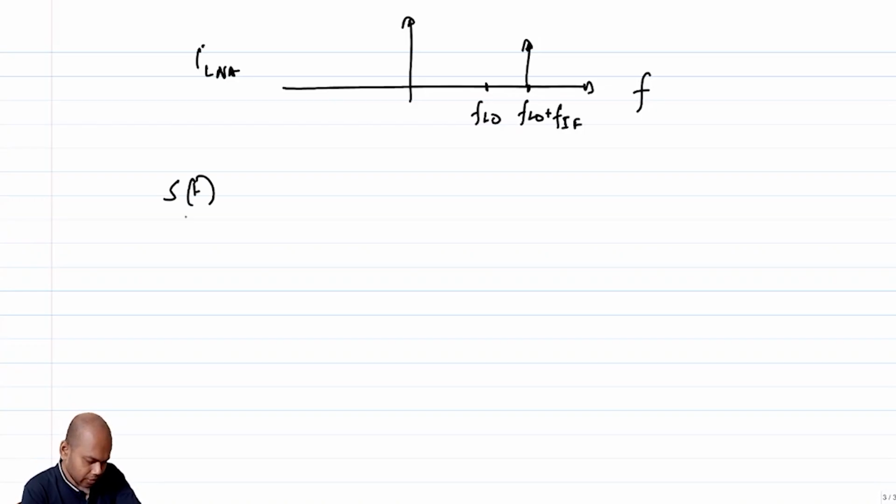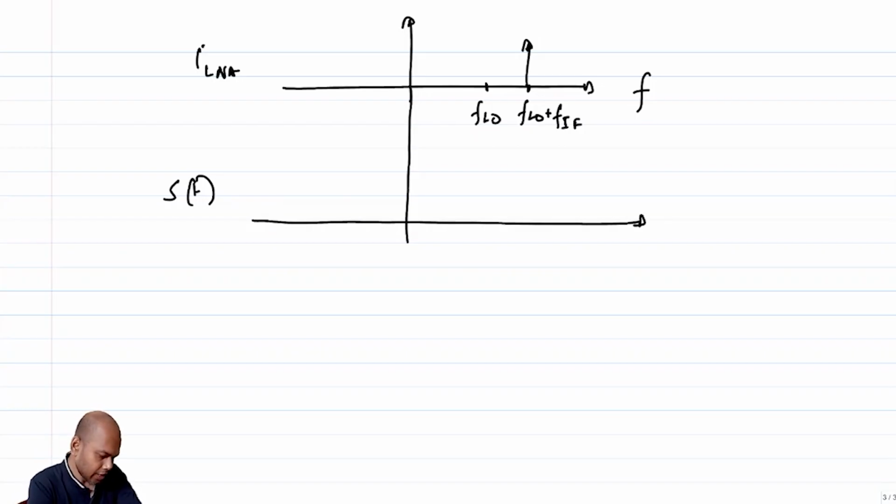What about S(t)? What components does S(t) have? S(t) clearly has a DC component, which I called, let's say, C0. S(t) will have a component at F_LO. If S(t) is a 50% duty cycle, where will the next component be? Will it have a component at 2 F_LO? No, it will not. So the next component will be at 3 F_LO, and so on.